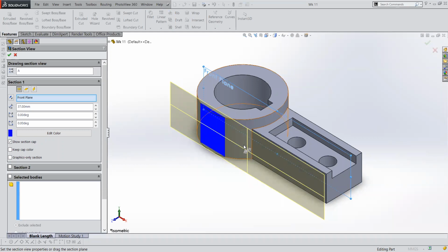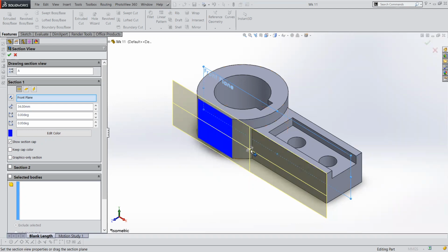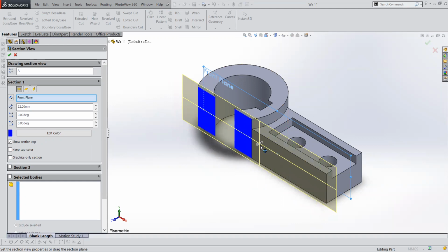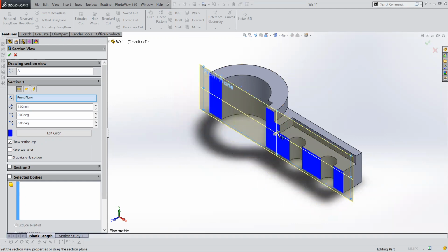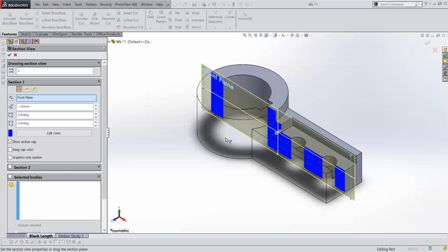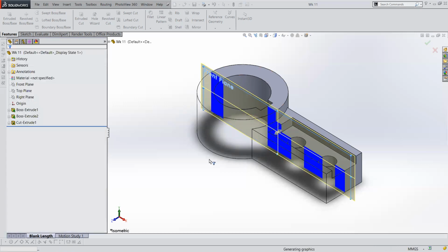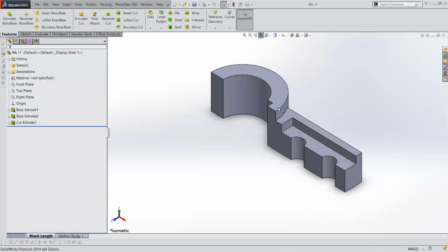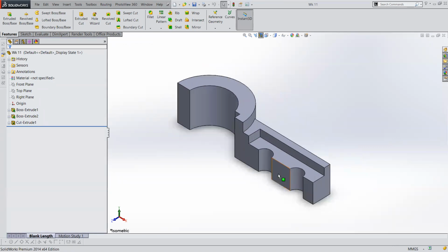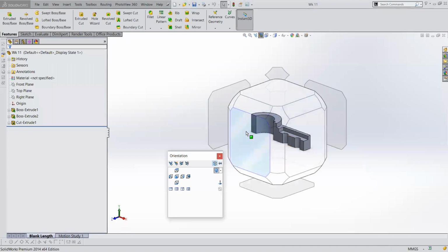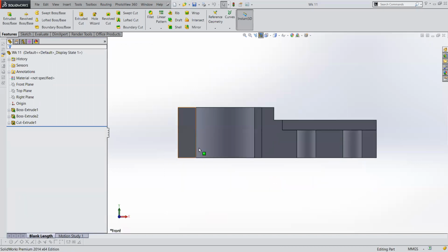Okay. So that is what you would see when you move the sectional plane further in. Now at halfway, or where the sectional plane is in our activity, this would be the isometric sectional view. All right, and then our front elevation would be looking from the front. This is our section. These hatched lines show a sectional cut.